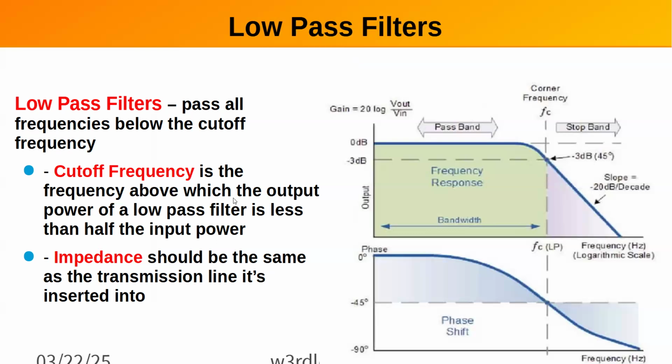And the impedance of the filter should be such that it matches whatever you're feeding it with. So if this is a filter, like a low pass filter on the output of your transmitter, it's probably going to be a 50 ohm characteristic impedance. So you design the circuit that way by the way you choose R and C values. Because you can not only choose them for a particular frequency, the ratio of them determines what that impedance is going to be.